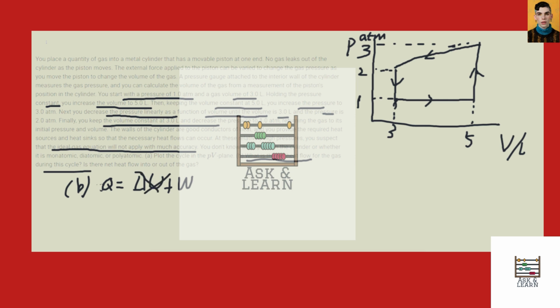So basically, Q is simply equal to W, and the work W equals the integral of PdV by definition. If we do the integral for the cycle, you will see that this integral just represents the area enclosed by this loop.